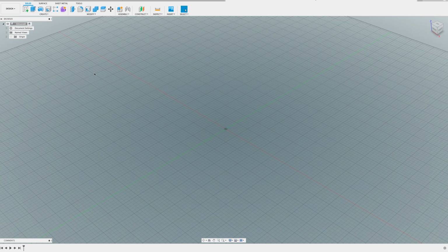Okay, so in this project we're going to basically utilize all the tools that we have already done, which are a revolve tool, the sketch of the profile, and then we're going to do the extrude tool, which is what we did when we made the dice. And finally, we're going to learn how to do some sketching of what's called an array, or a revolve on a 2D sketch is what it is.